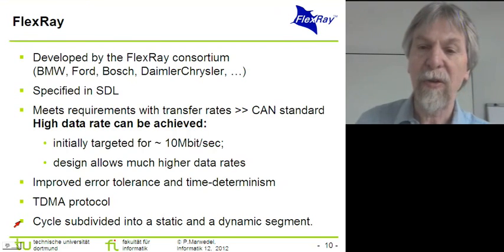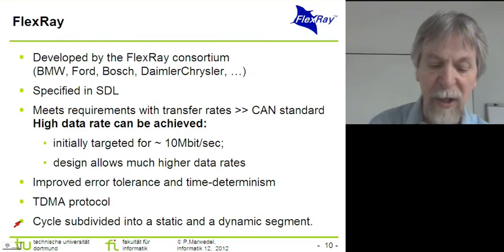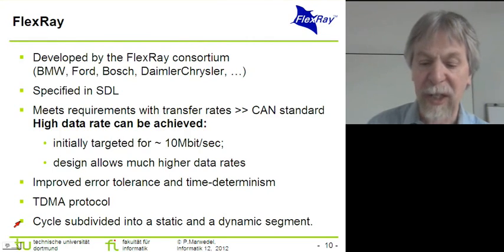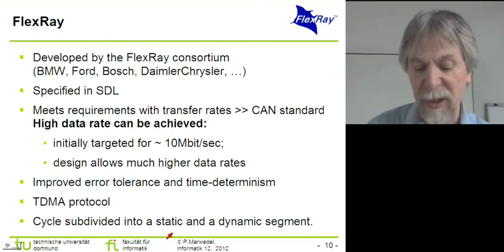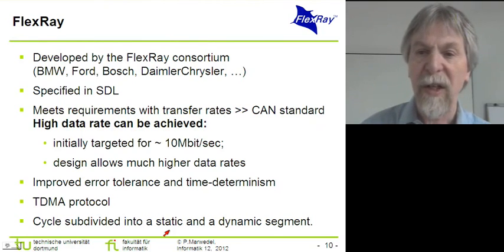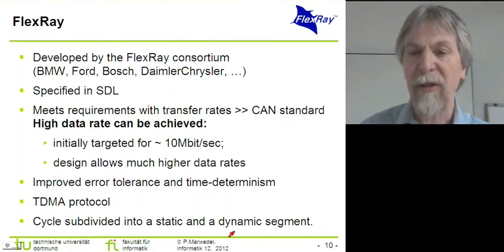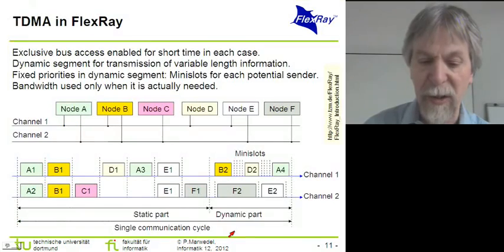In order to make the standard somewhat flexible, it is not just based on a very strict TDMA protocol, but there is some dynamic behavior there in the system. Therefore, each communication cycle is subdivided into a static segment that provides the guarantee for the real-time behavior, and a dynamic segment that would typically be used, let's say, for multimedia data.